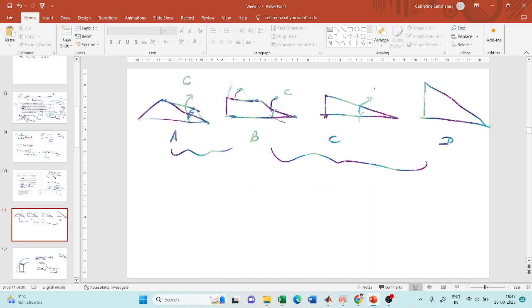But what is my super elevation? This slope will be just 2 or 2.5%. But what is super elevation? Super elevation is usually, so if I take this as E, super elevation, let us say, for example, I'll take it as 7%. Now this is only 2%.